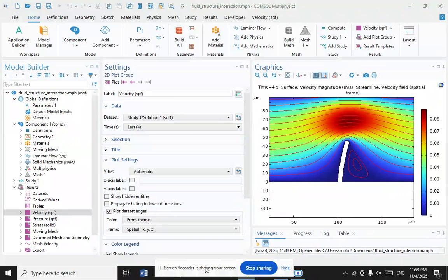This system is solved with block quasi-Newton iterations of the Gauss-Seidel type, and the Jacobians of the flow solver and structural solver are approximated by means of least squares models.